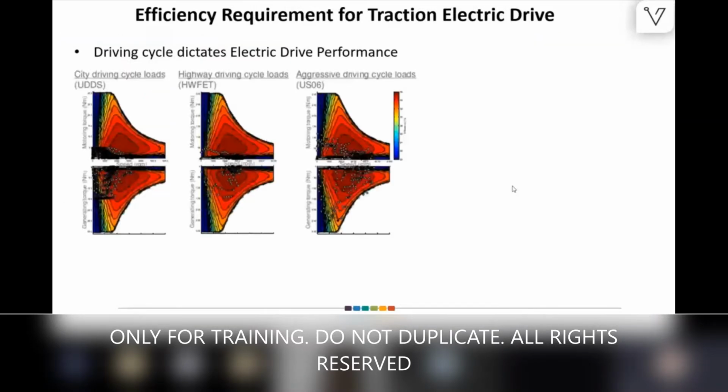So what is the first thing that comes to mind when it is a vehicle? Coming to something very specific to that vehicle, all that we discussed is a high level target, which may not be really dependent on the vehicle that we are considering. But the moment we come to the vehicle level, the drive cycle is the key element. And this is a torque, speed, and efficiency plot. What we will be doing, this is called a heat map, and we will be plotting those drive cycles